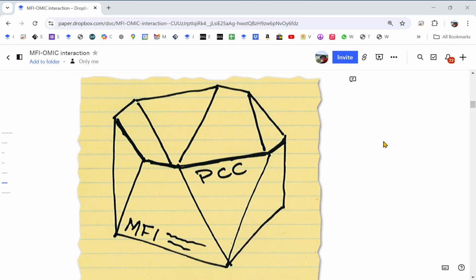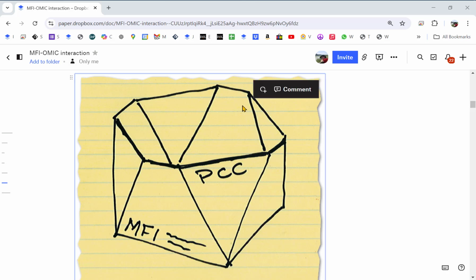So to do this, we're going to create this box out of sheet metal. That's cutting something flat and bending it into shape. So this design looks like it has a faceted shape that, if we were to extend this top surface up, would consist of two rectangles. The square base at the bottom will be roughly 4 inches, and the overall shape might be as high as 5 inches, but we're not sure exactly how far we want to cut it down to get this look.